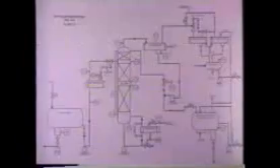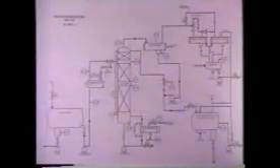There are temperature sensors located at various points along the column. These sensors enable the inside operator to closely monitor the temperatures within the column. During startup, as well as during normal operation, the operator controls the temperature at the top of the column by adjusting the reflux flow controller. This controller regulates the amount of reflux going back into the column.